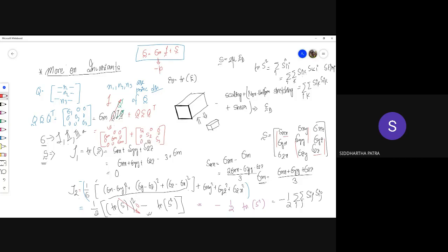That means the same set of orthogonal tensor that diagonalizes the stress tensor also diagonalizes the deviatoric stress tensor. Or in other words, the principal directions of the stress tensor are also the principal directions of the deviatoric stress tensor. So that means, with reference to us being able to represent stress like a vector, we can do that as a sum of the hydrostatic and the deviatoric part. The hydrostatic part having an identity tensor in itself, any set of orthogonal basis will diagonalize the identity matrix. So the principal directions of the stress tensor will also do the same.